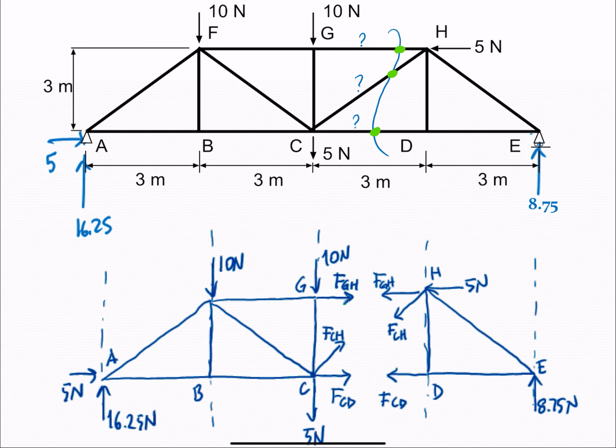Before we decide that, nobody told us what sort of forces we have in the cut, so it's up to us to analyze it and assume the sense. A preference of mine is to always assume that the forces are sticking out from the members. Just a personal preference. Once we apply the method and obtain our forces, if some of them are negative, that means the forces were reversed.